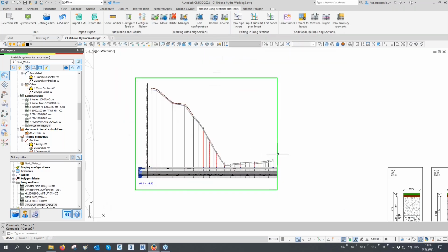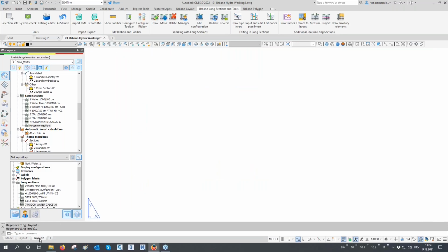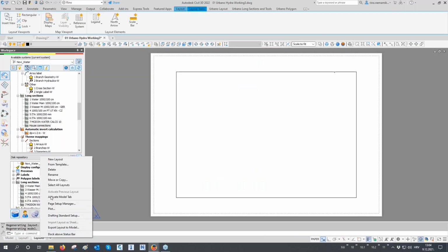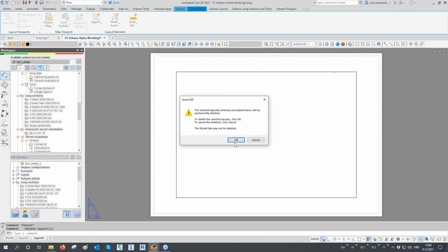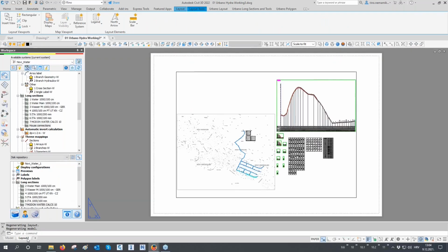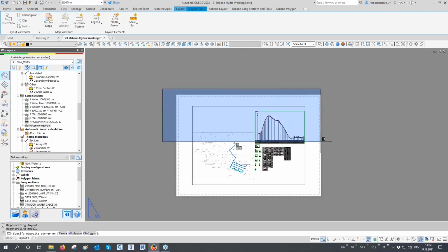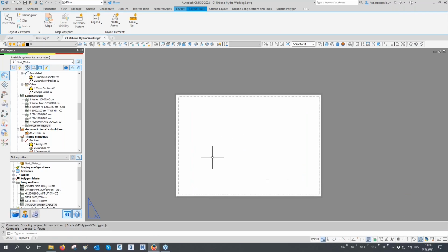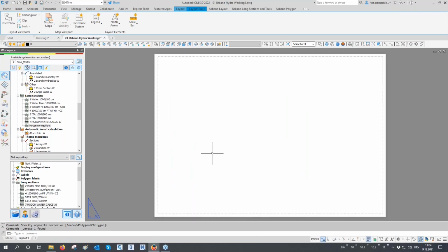Okay. Also, you can go to the AutoCAD layouts. I will delete this layout number 2. Let's go here to layout number 1. This is not essential. You don't have to modify the layout, but I like to do it. So I like to put the paper in the AutoCAD layout that I will use for plotting.